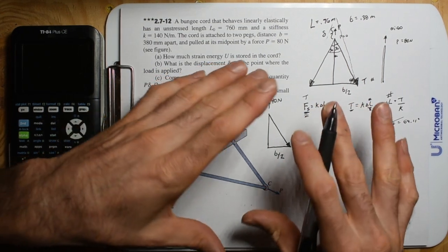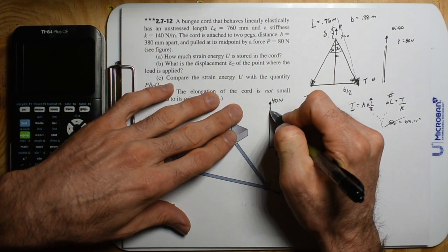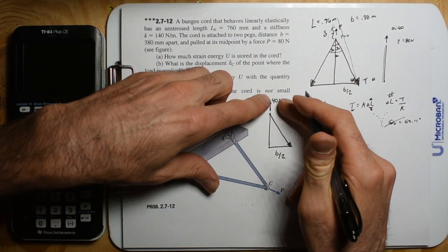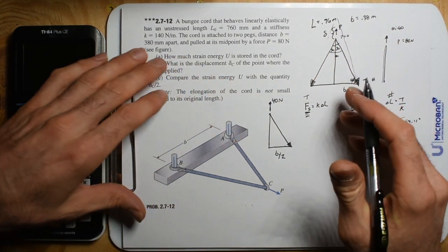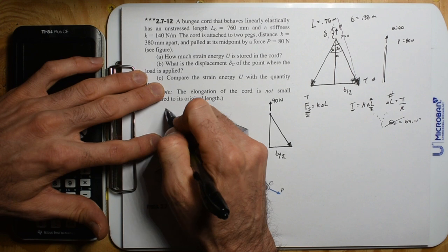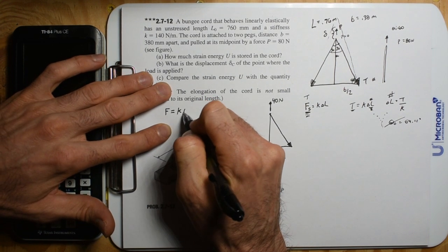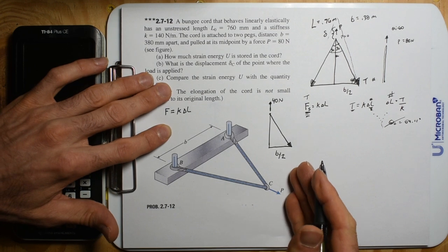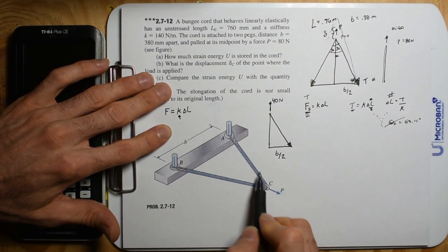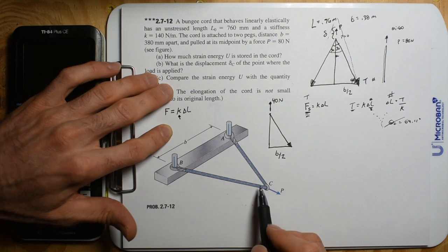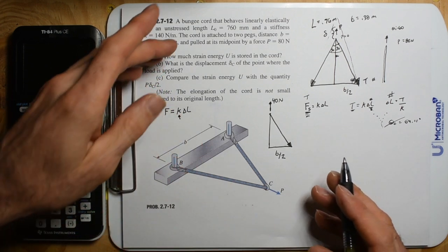So now we're talking about the final, you know what I mean? Because that was the whole deal. If we're taking the free body diagram from when we put 40 newtons on, well, guess what? This already stretched. Now, the thing to not get confused about is the spring force is K times change in length. And this K has to involve the entire length.